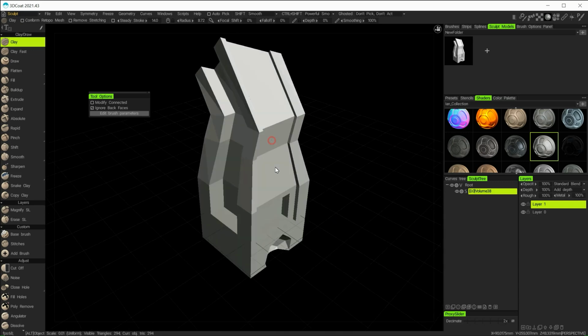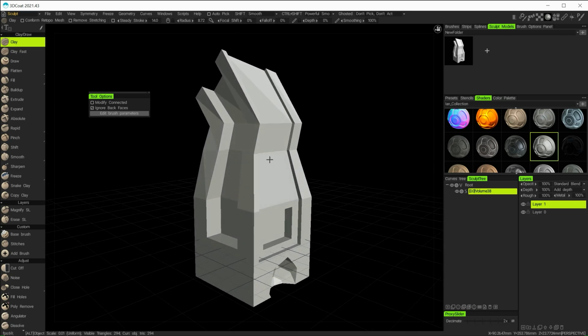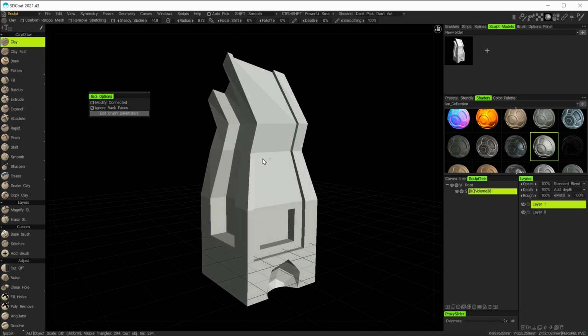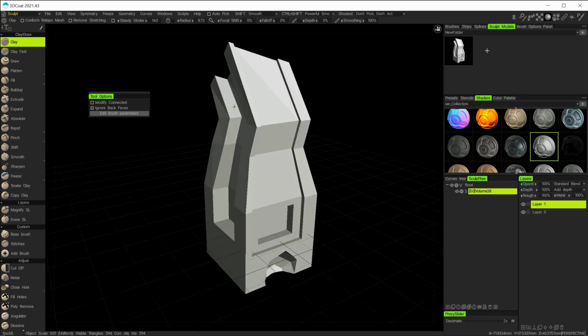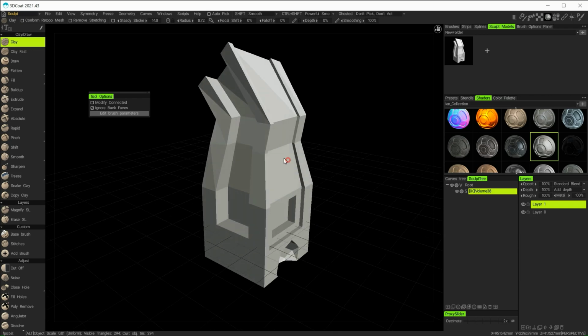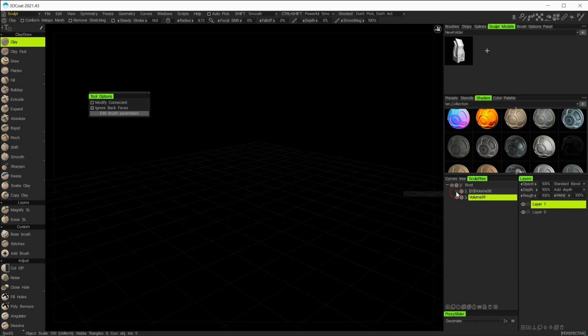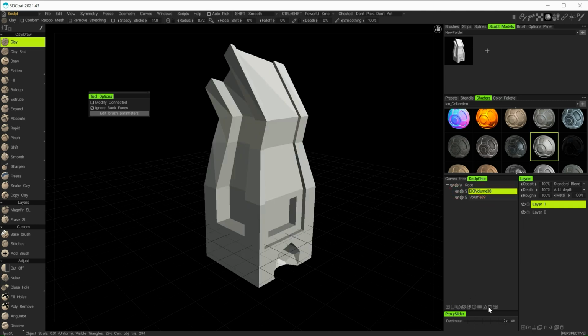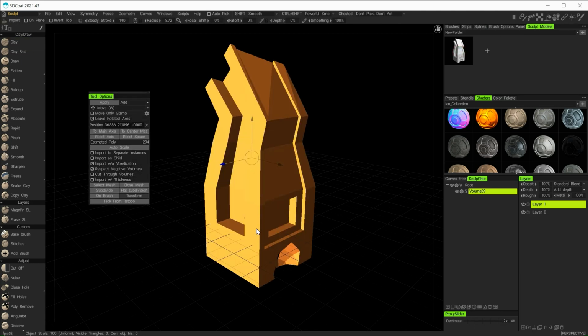So at this point I've got a low polygon object in a Sculpt workspace, which isn't really that much use to me. So what I'll do is I'll just delete this one and make something a little bit more appropriate for sculpting. So there's my object, I will just delete that one. Click back onto this object again to bring in a fresh one. Again, I get my yellow color indicating a proxy object, so it needs me to do something.